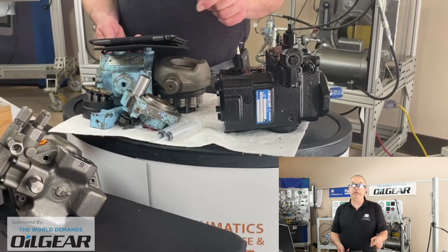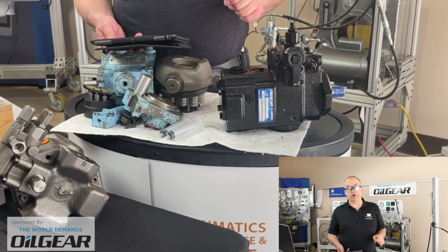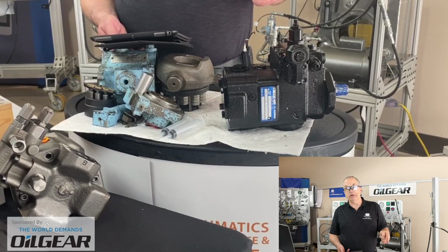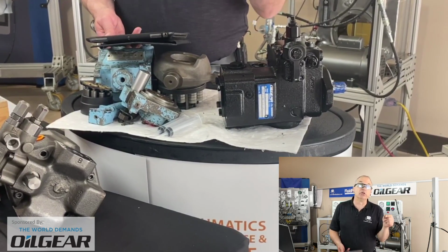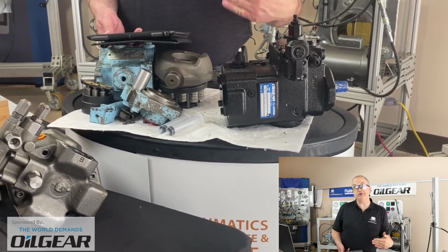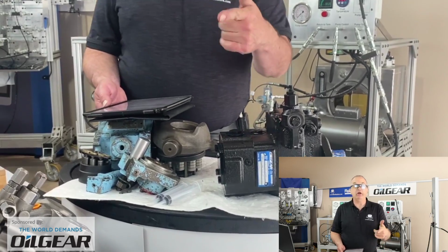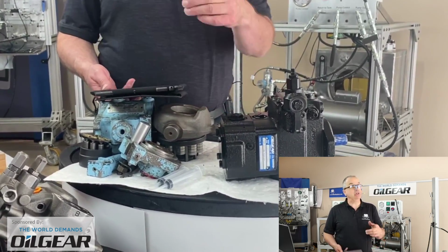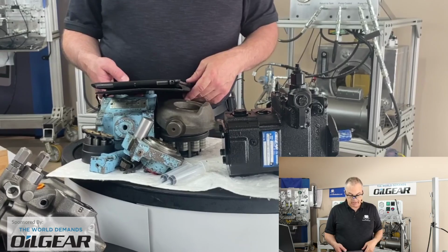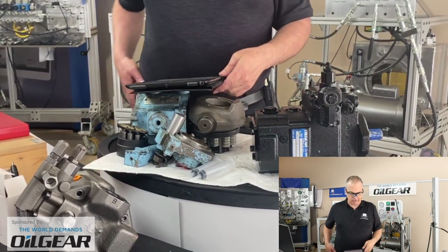That doesn't mean we haven't seen it. We came across one stationary installation a good number of years ago where variable frequency drive motor and load sense piston pumps were used together. And yeah, that became quite a tricky system to create the right control schemes for. It is doable though. Lots of energy savings available. It is doable for some hydraulic system designs. Depends on the application and the usage.